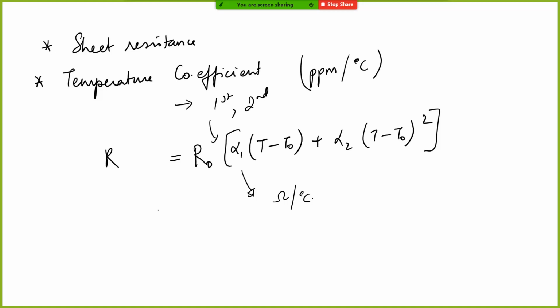So you rationalize it to a million, or rather in this case you might multiply by 10 power 6 and then give that number. How are you converting that ohm to ppm actually? I want to show you the data sheets of this one. I think it will become clear there.